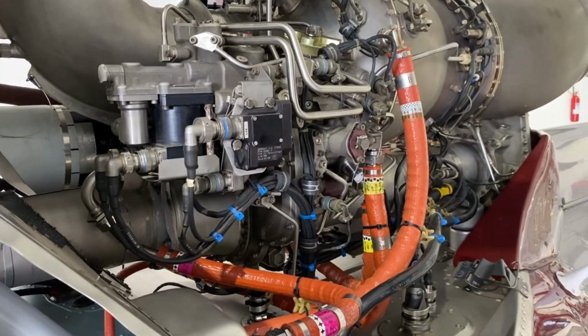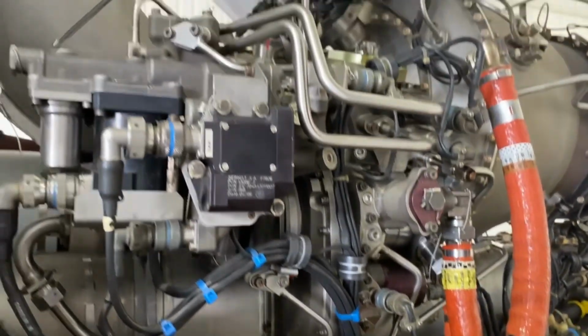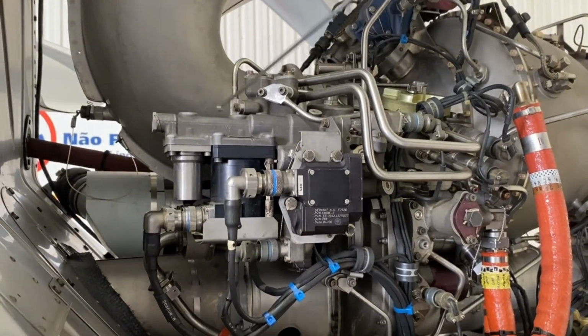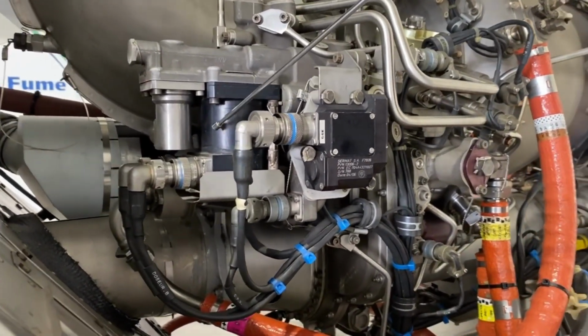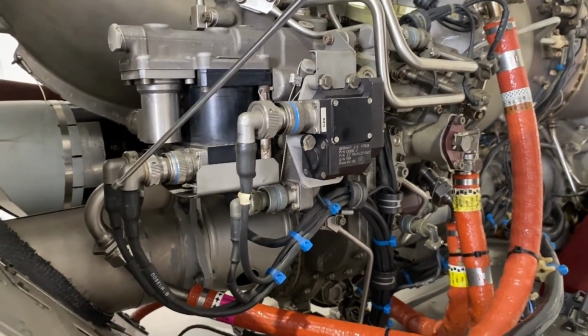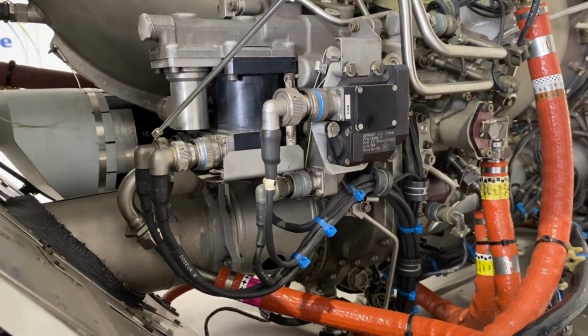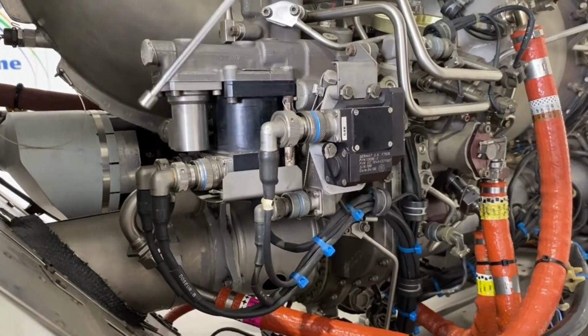So then the fuel reaches the high pressure pump and comes to the HMU's metering unit. The metering unit has a needle which is controlled by this stepper motor. In fact, it has two controls, two coils, one for channel A and one for channel B. The input from the ECU, from the DPU, from the digital engine control, arrives here and stays there in the housing.